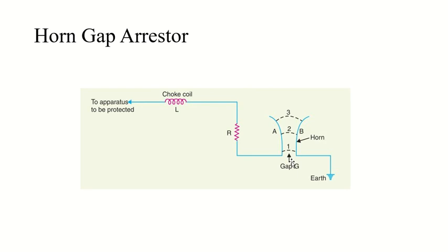The heated air around the arc and the magnetic effect on the arc cause the arc to travel up the gap, and this arc will move progressively into positions 1, 2 and 3. These three positions you can see here are not just normal numbers, they are different positions for movement of the arc. At some position of the arc, most of the times position 3, the distance may be too great for the voltage to maintain the arc. Consequently, the arc will be extinguished, and the excess charge on the line is thus conducted through the arrestor to the ground.